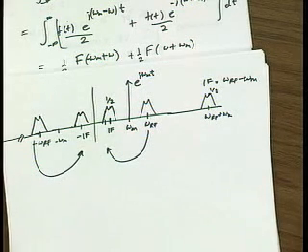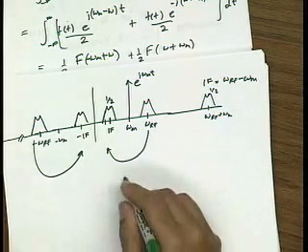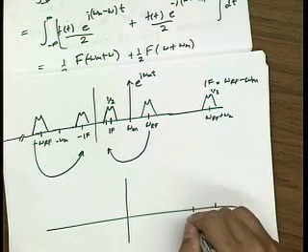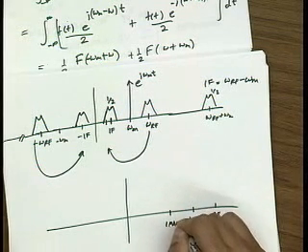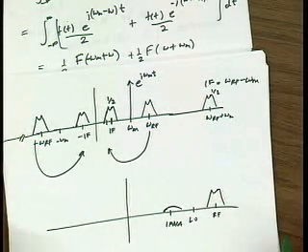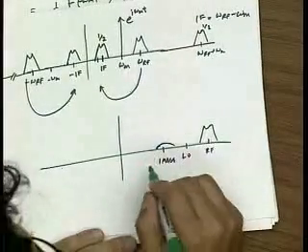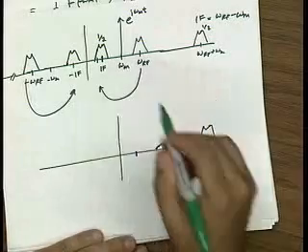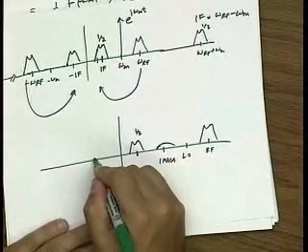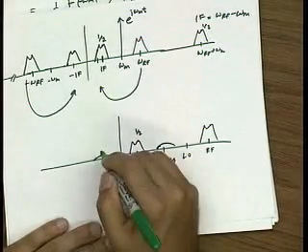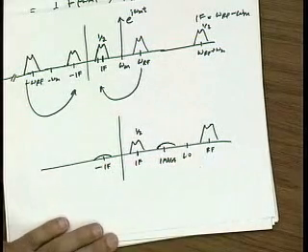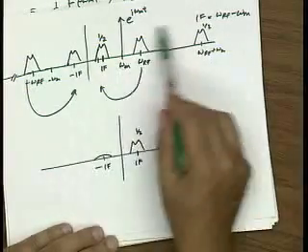What if I had, this is a bad picture. Let me draw a slightly better picture. This is the RF, this is the LO, and now this is the image. So let me say I have a signal here, and let's say I have some noise signal here. So due to the multiplication by this, my RF moves here with a factor 1/2. My image moves here to minus IF. So that's what happens when I multiply this part of the spectrum by this.